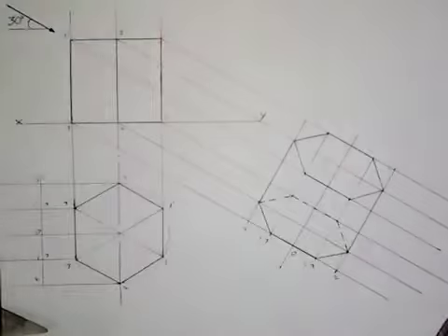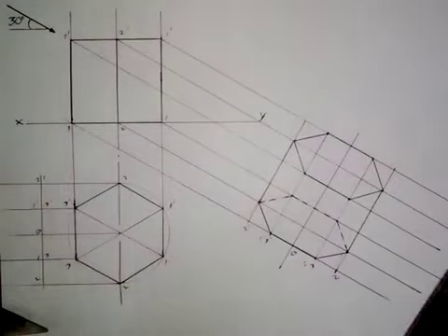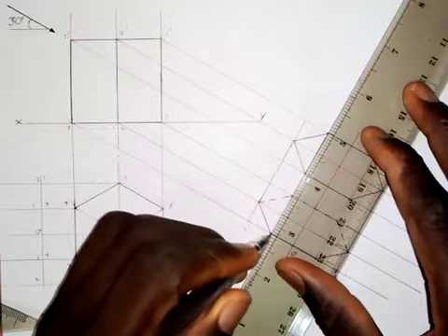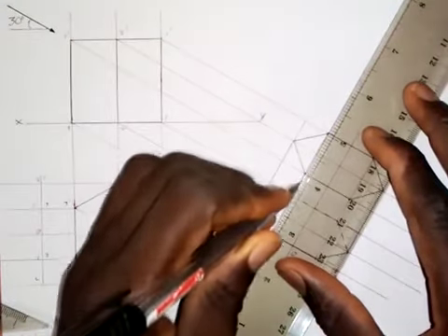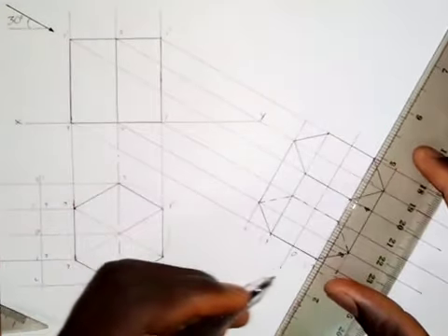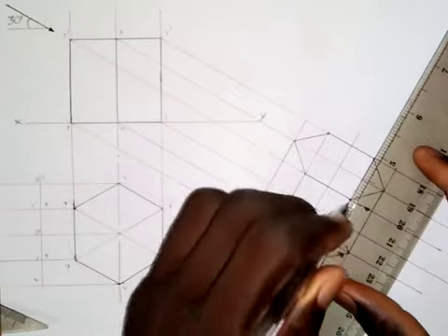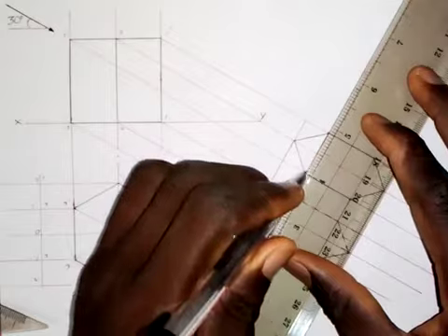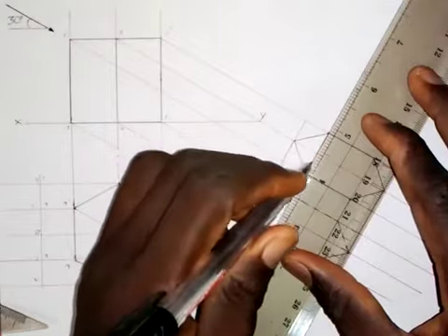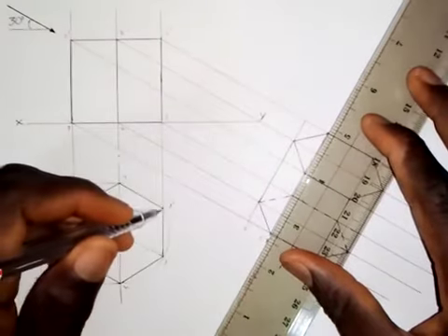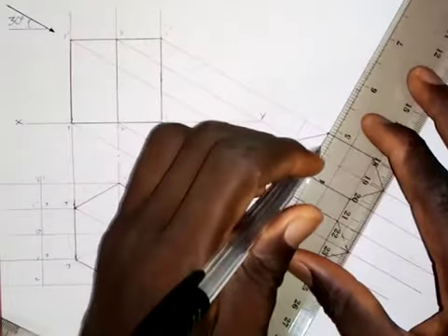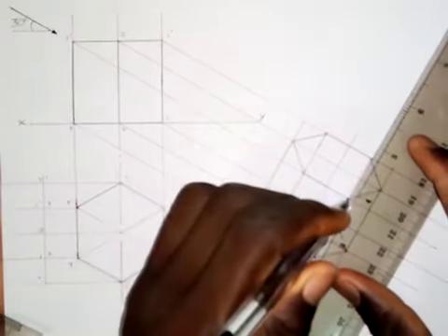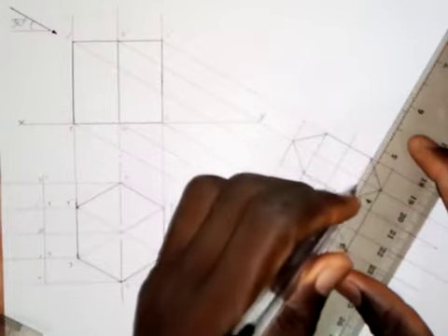Alright, so this is how the auxiliary plan looks. And then, okay, we are not done with that. We also need to join this together. So 3 to 3. We join this together, and also we join this 3 together. Then we have this part here. This line will be drawn with a short dashes line. This line will be hidden from us. The line at this point will be hidden from us, so we draw it with a short dashes line. The same thing applies to this. We draw this with a short dashes line.